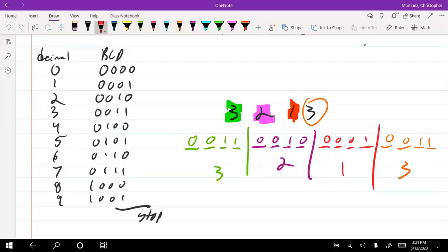So that's a way that we could take each of these digits, and instead of converting it directly to a binary number, I take every decimal digit, and I represent every decimal digit as a code. So I know this ends up being a lot more bits than I would take as a binary number, but it might be easier for me in the problem I'm trying to solve to keep everything as decimal. All right, so that's what we can do with binary besides saying it's a number. I can use it as a coding scheme.